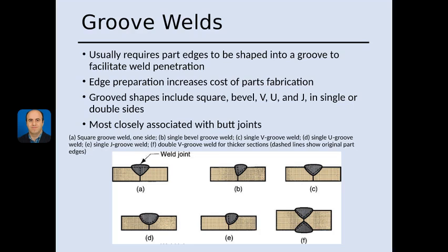In the groove weld, we have more penetration. The strength in the groove weld is higher than the fillet. For thicker material, groove is preferred over fillet.